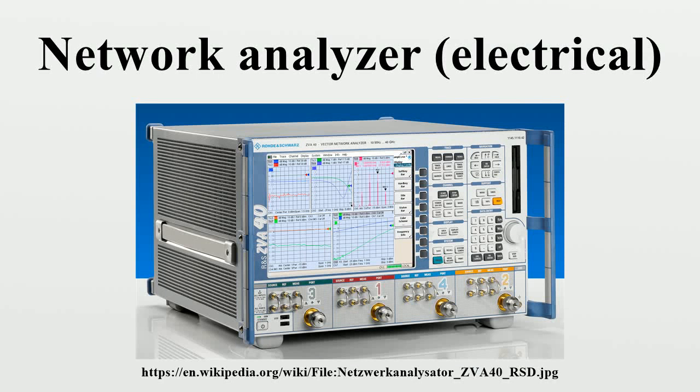A network analyzer is an instrument that measures the network parameters of electrical networks. Today, network analyzers commonly measure S parameters because reflection and transmission of electrical networks are easy to measure at high frequencies. But there are other network parameter sets such as Y parameters, Z parameters, and H parameters. Network analyzers are often used to characterize two-port networks such as amplifiers and filters, but they can be used on networks with an arbitrary number of ports.